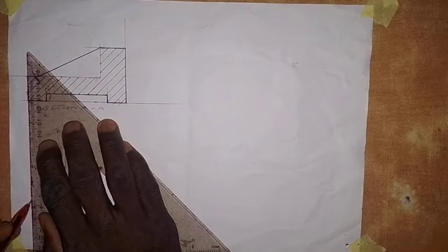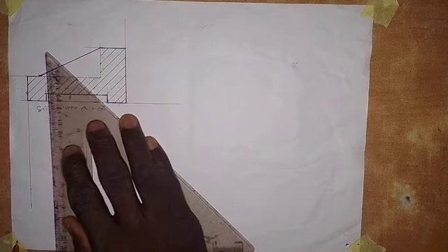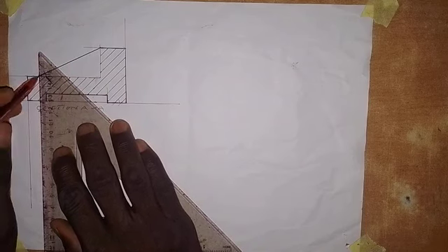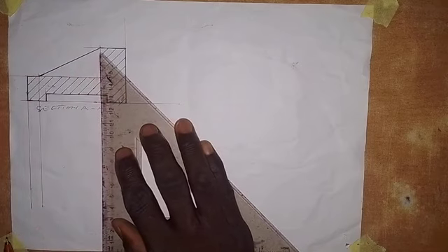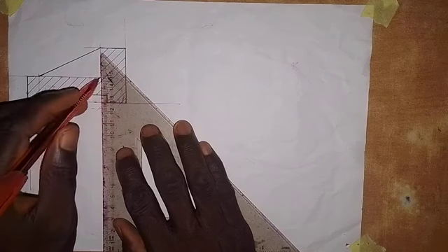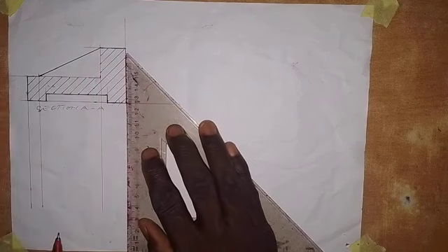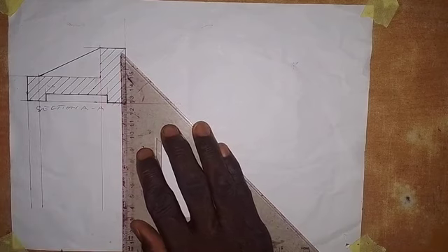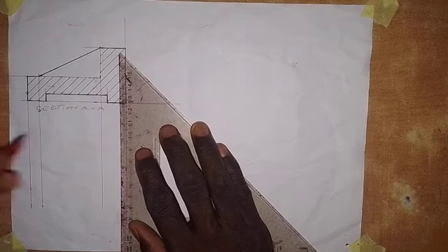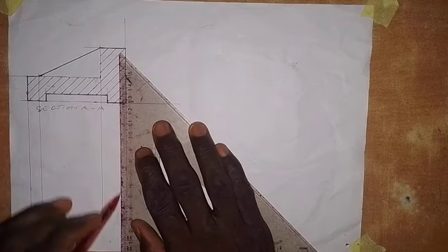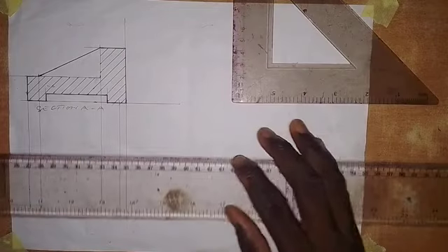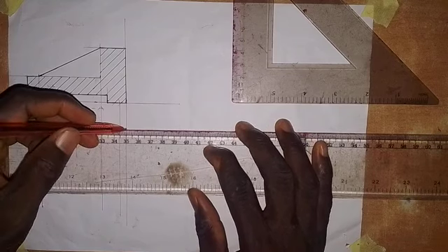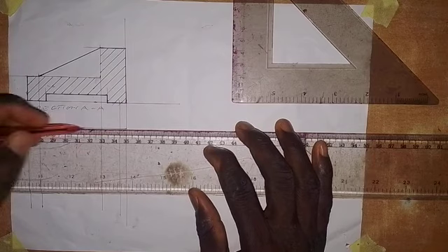Also at this point, for the web, I'm going to draw a vertical line down here. Then at this point, I will also draw a vertical line down. Coming to this point here, I will draw a vertical line. So that 5 millimeters that we took, which we didn't use in the section AA, we need to draw a vertical line down, and then I will come up here and draw a horizontal line, just like we are drawing the orthographic view.